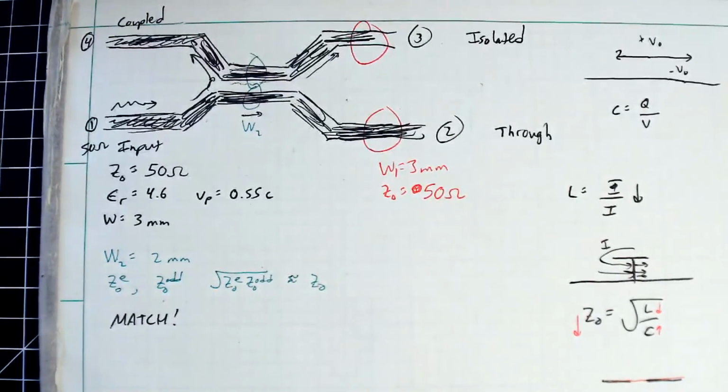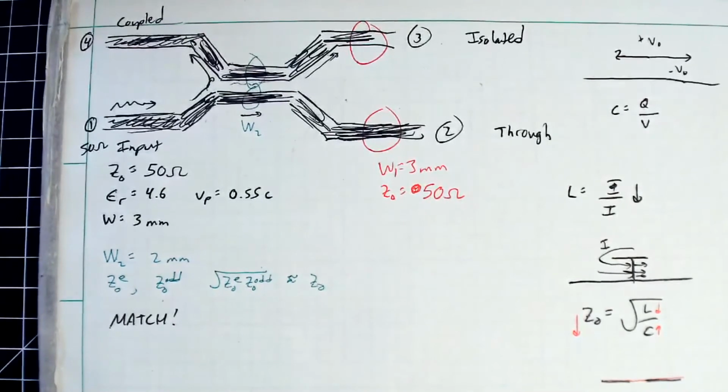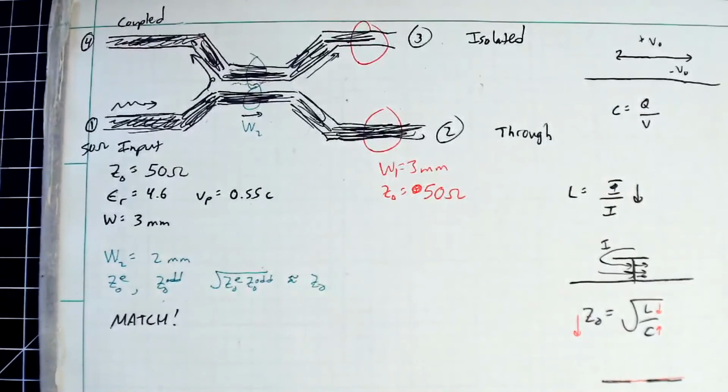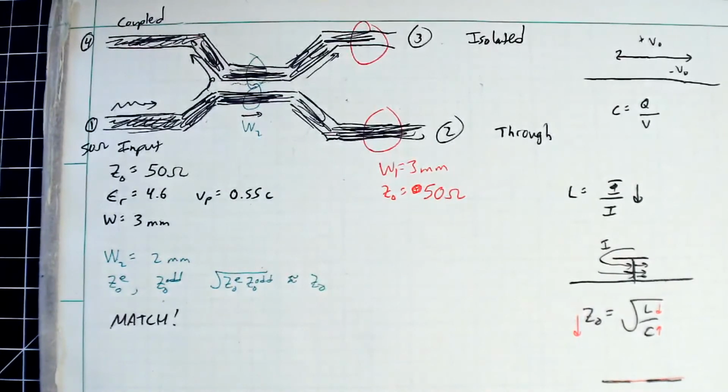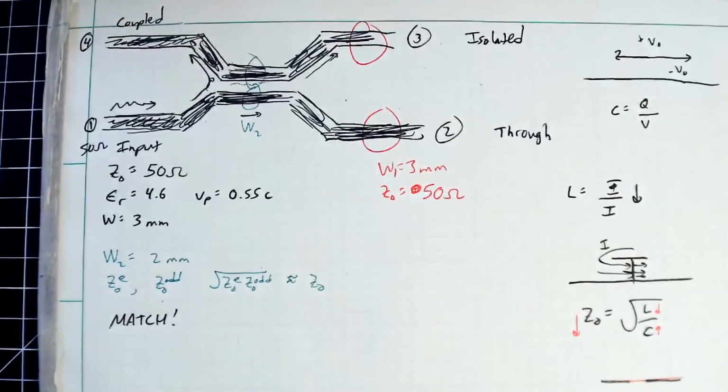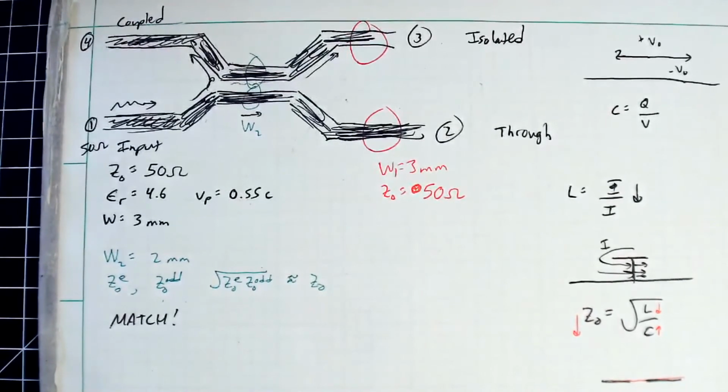So ZX, so you see it didn't really change it very much. I just almost doubled their separation there. Whereas before it was 1.28, 5.1. So it barely changed by like a half an ohm to separate them like that. So it's pretty insensitive to that distance as far as I can tell. So that kind of blew my mind. So they will couple more or less, in your even and odd, but yeah, that product between them won't really change a whole lot. So yeah, that's kind of a weird